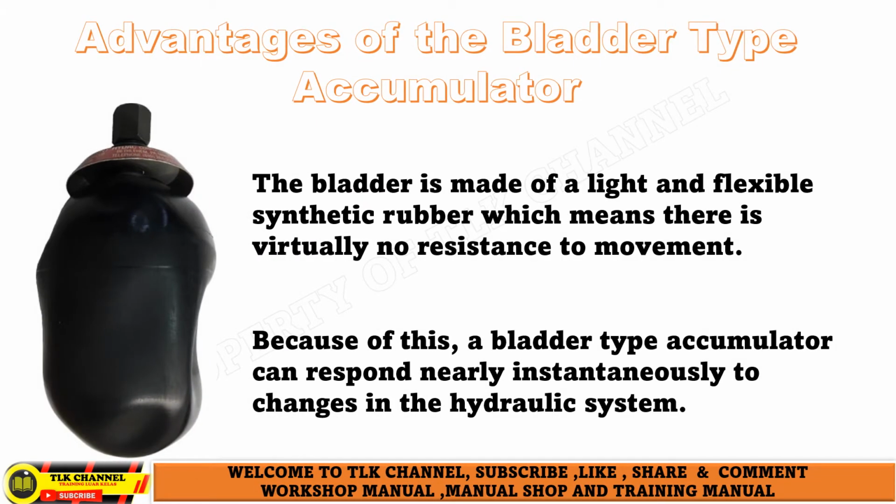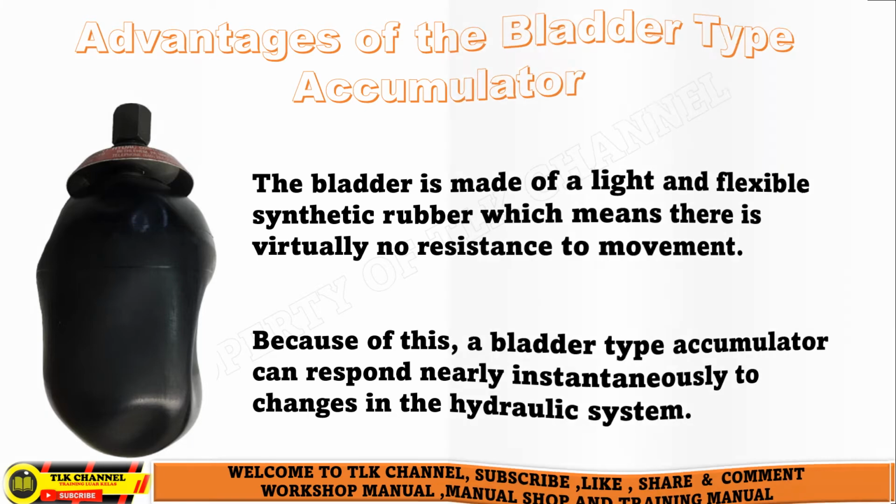Advantages of the bladder-type accumulator. The bladder is made of a light and flexible synthetic rubber, which means there is virtually no resistance to movement. Because of this, a bladder-type accumulator can respond nearly instantaneously to changes in the hydraulic system.